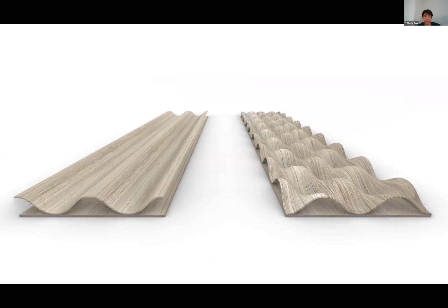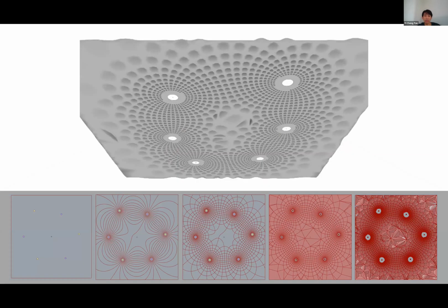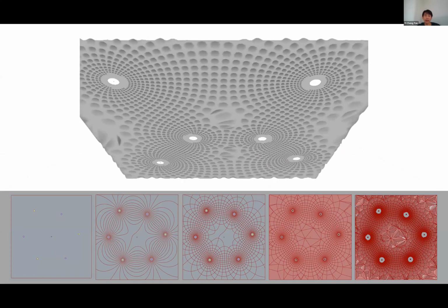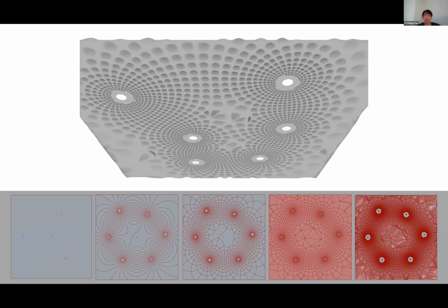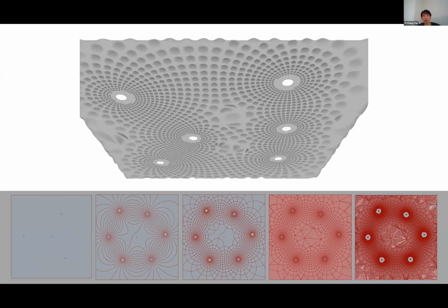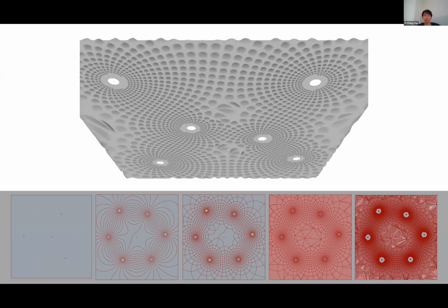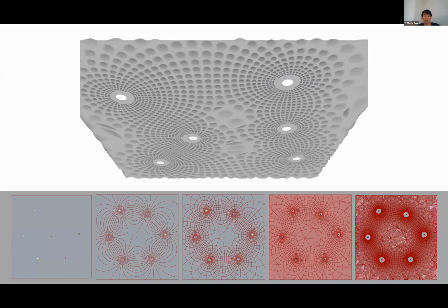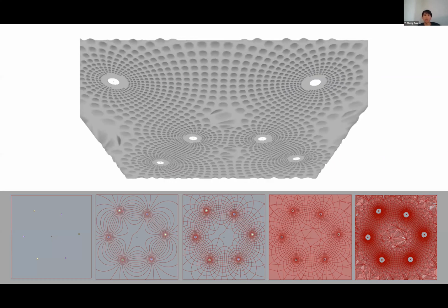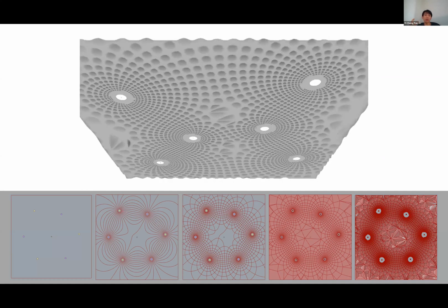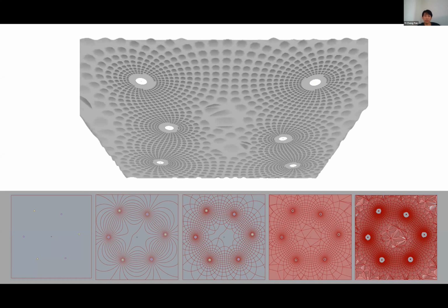So this product, we are working on this in collaboration with OneWood, but our idea is to turn them into wall and floor panels that can replace RC precast panels. So the idea is to create this waffle that eventually we can vary how the waffle is organized in order to bring the load to different points where the load can transfer downward. So trying to create more design freedom where we do not need a regular column grid.